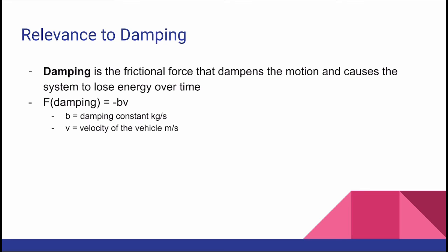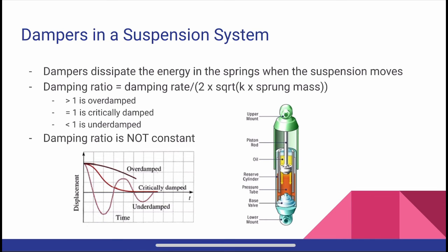For a car traveling at high speeds, damping comes from the hydraulic dampers present in the suspension system. They are composed of a piston inside of an oil-filled cylinder. They work to dissipate the high amounts of energy in the springs. When there is no change in energy in the springs, like when the car is at rest or at constant acceleration, the dampers have no effect.